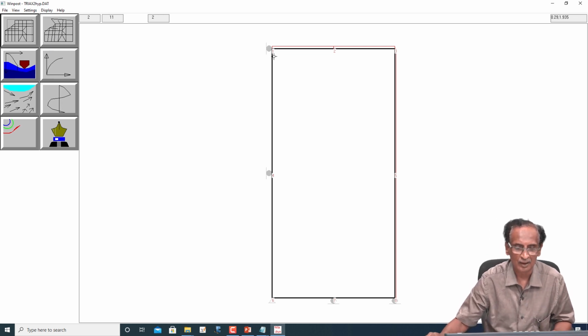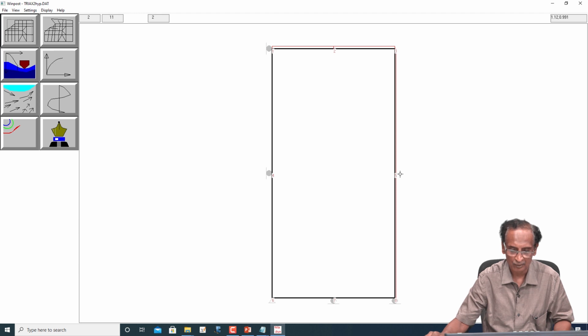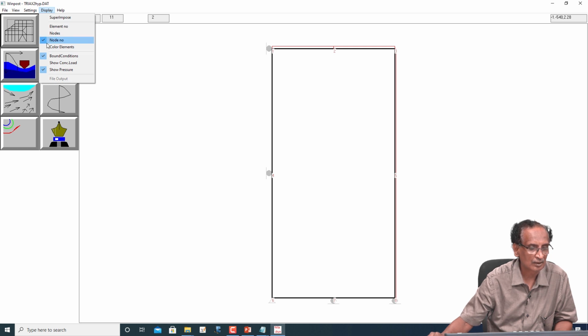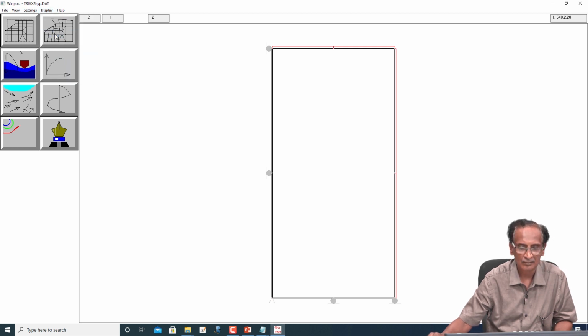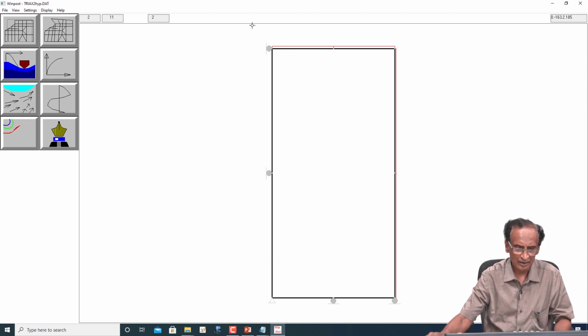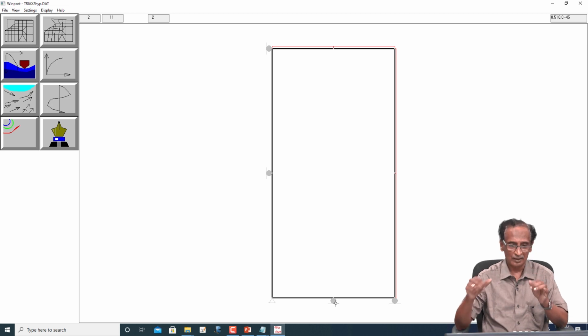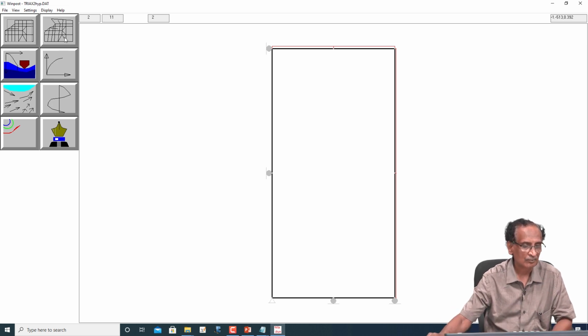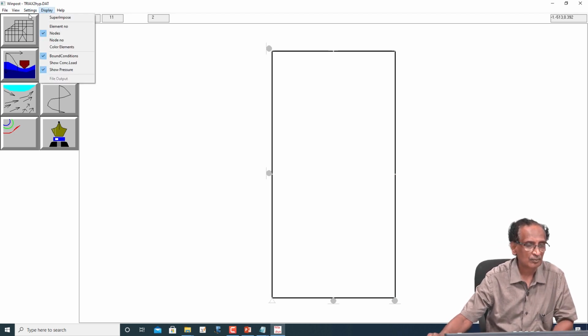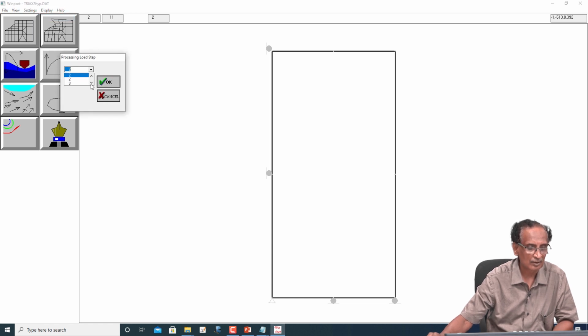These are the node numbers 1, 2, 3, 4, 5, 6, 7, 8, and let me just delete the node numbers. And on the symmetry plane, it is a roller boundary condition, and on this horizontal plane also we have the roller boundary condition, so that we have smooth rigid boundaries, and then we are applying strain. Okay. So, let me just go to the last load step.